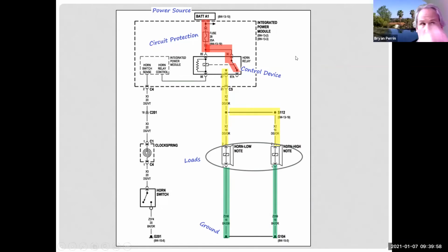Well, the reason why I don't want to necessarily pull the relay is I want to also monitor the relay function at the same time. If I didn't have that, then yes, I would have to pull it out and I could check for power here. I could apply power here or see if there's ground. And I'm going to draw out this other side of the circuit in a second. But the problem is that I've seen open circuit potential. So for example, I could see power at pin 30. And if I power this up from another source, I really haven't tested the integrity of the connections at the fuse or the connections through here, because all I'm checking is open circuit voltage.